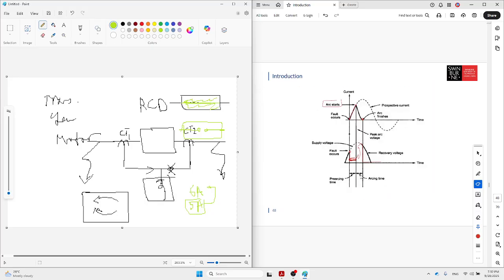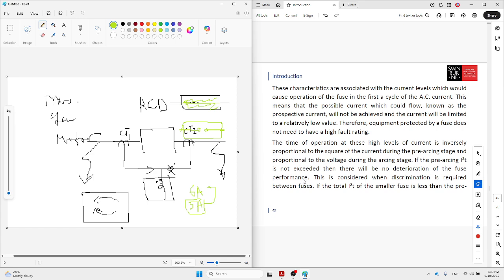for you. Of course, different manufacturers have different standards, but whatever is available in the market, you cannot go to the market and ask them for your specific value. So step one, the most important step, is the nominal current of the fuse, then the nominal current of the device. So nominal current is the most important one, step one.